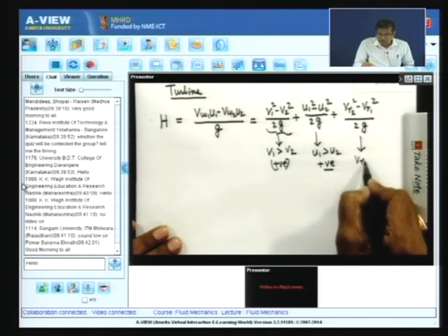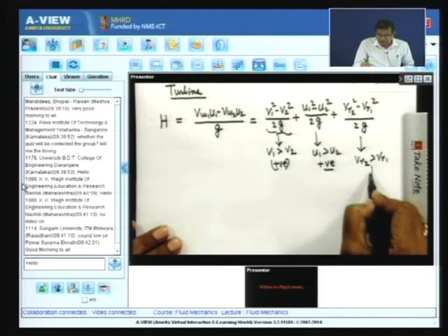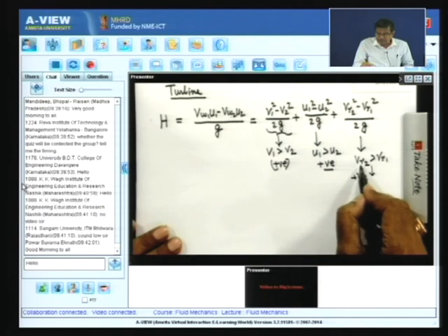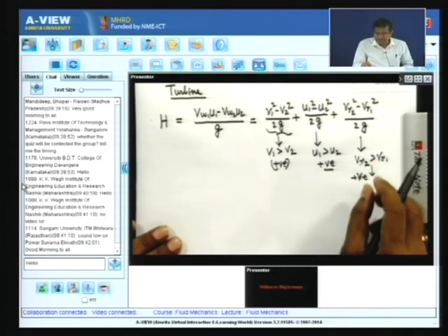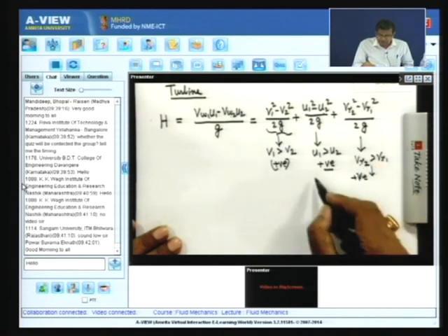VR2 has to be greater than VR1. That means, when it flows through the runner blades, the relative velocity, that means the velocity relative to the runner blades, has to increase at the outlet from the inlet. That means, this should provide a converging passage of the flow through the runner. So, with this concept we proceed.